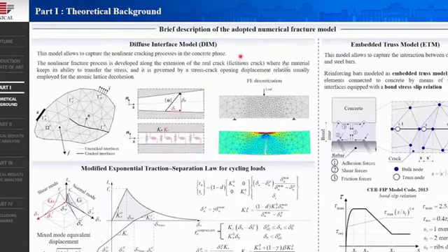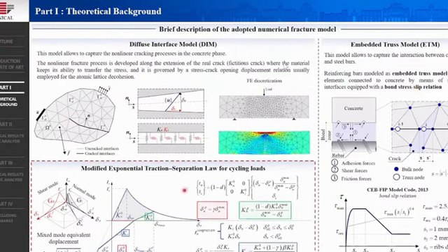Here, I'm going to describe the adopted numerical fracture model, which is based on the combination of two different numerical techniques. The first one, the diffuse interface model, allows to capture the nonlinear cracking behavior in the concrete phase, and the second one, the embedded truss model, allows to capture the interaction between the concrete and the steel bars.